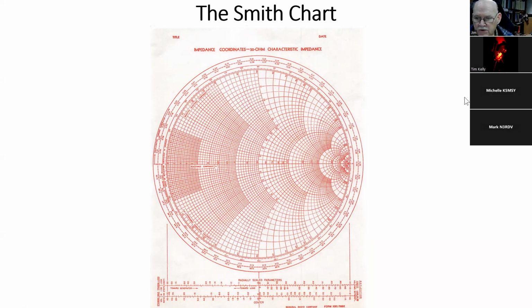And then you see these other circles that are tangent to the horizontal line. The perfect world would have them go off here to be a full circle, but we don't need them. Those are curves of constant reactance. So given a complex impedance of an antenna, you can plot the resistance and the reactance on this chart. Say here. Oops.